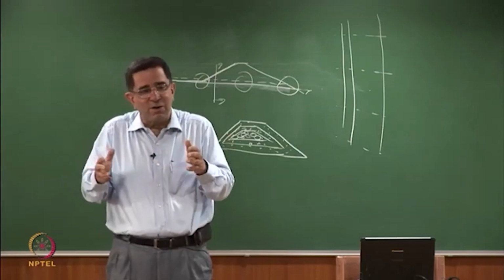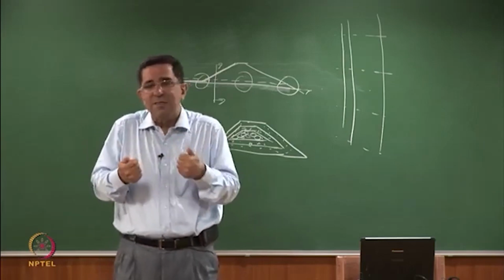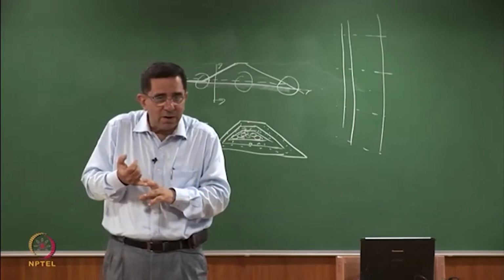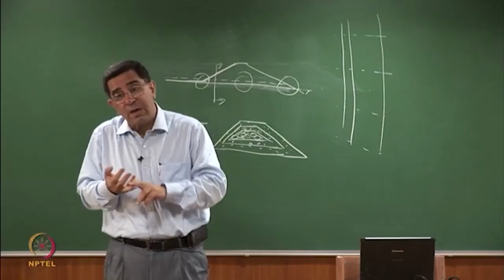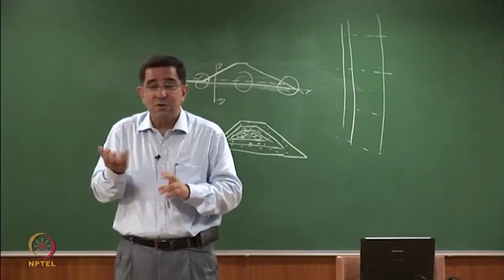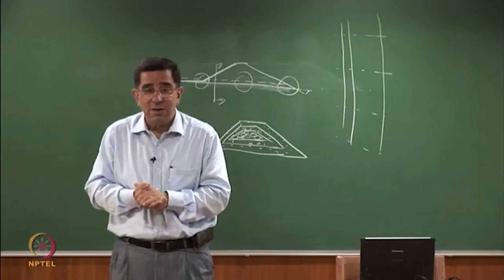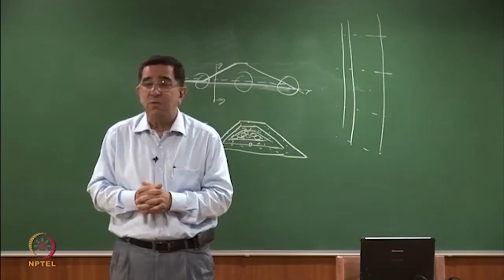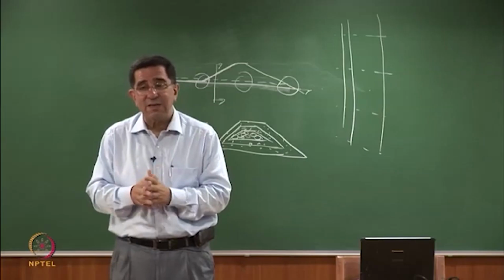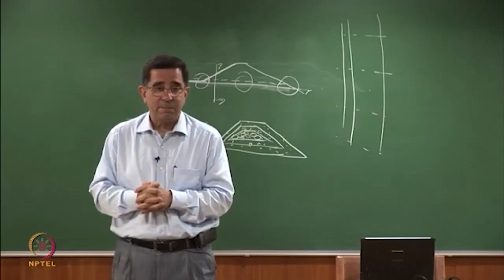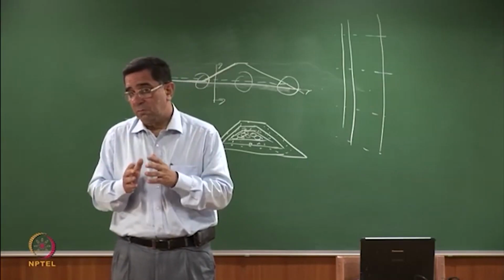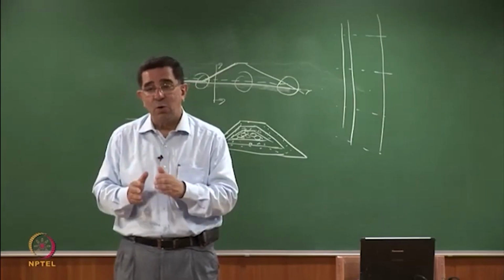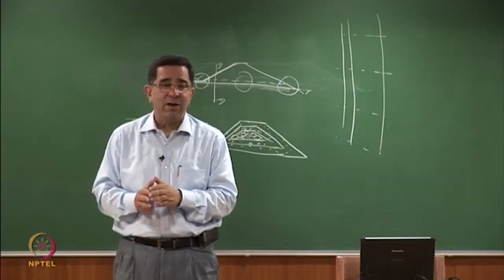And as long as slurry water comes in, there is this problem of stability, because you can always have either a piping failure or earthquake induced failure, because it's a soft material, and in slope stability analysis you will find out that you can always have liquefaction in the silty sand, sandy silt, which has not been compacted. So be careful, keep the phreatic line under control, keep it low or keep it well drained, and no fines should come out.